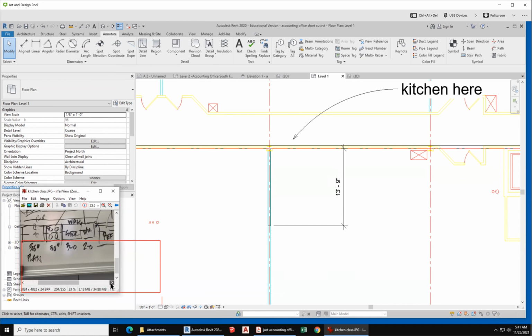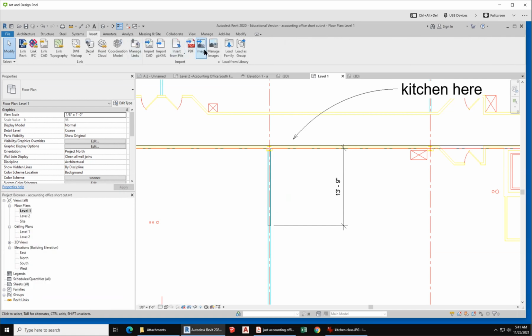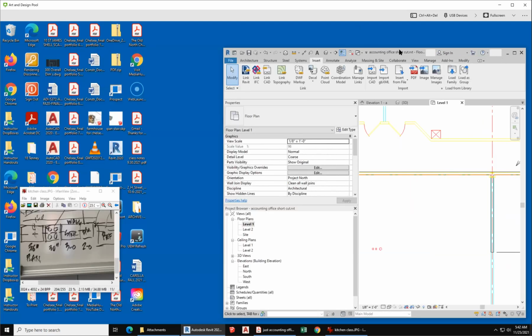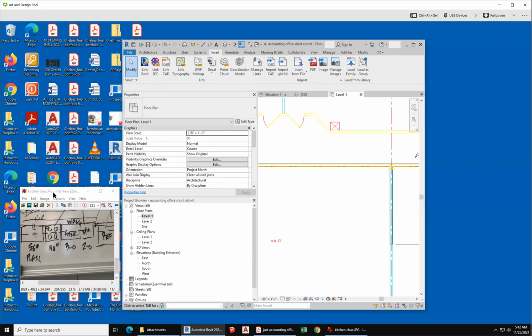And clear, look at that, it fits in that window. Let's clear the annotations. Close my annotation to get back to Revit. Insert, load family. So we had to hide that drawing. It's drawn behind the Revit screen here. So let's do something creative. Let's make Revit a little smaller so you can see both at once here.